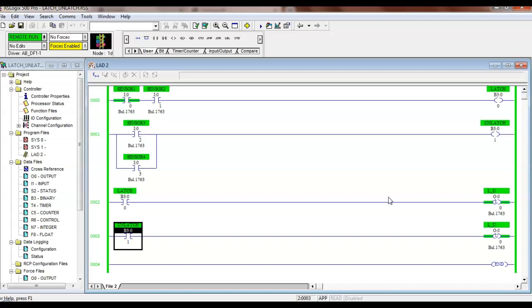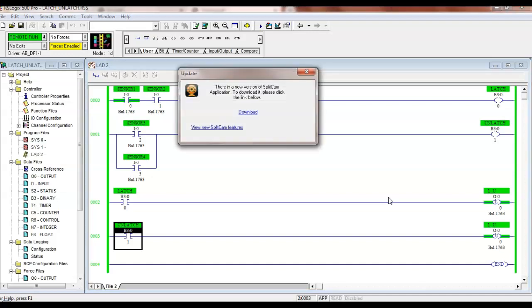And that's one of the things I told y'all. When RSLogix 500 came out, the primary people programming PLCs was electricians. They didn't understand memory. They understood ladder diagrams. They understood control relays. They picked up real fast on the B3 files, right? Because they said, I've only got 15 outputs, and here I've used 15 of them that don't do anything to the outside world. But they didn't know how to manage the memory in the computer. They had no idea what RAM was, ROM was, what drivers were. But now, the new PLCs, you manage the memory.